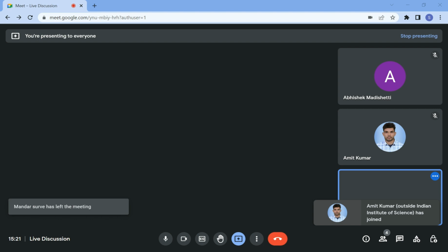And if we are saying that this line is inclined to VP and I'm rotating this, then whatever is getting rotated is actually the projected length. So this is the angle with respect to VP, and whatever is getting projected, that length remains constant. So the true angle with HP is theta, let's say, and the true angle with VP is phi.